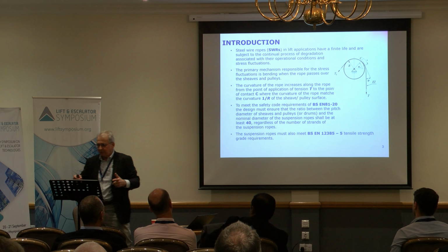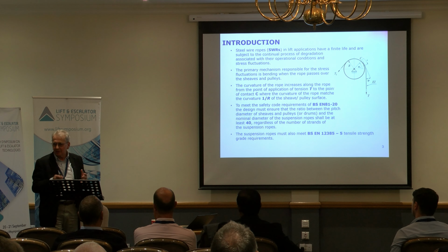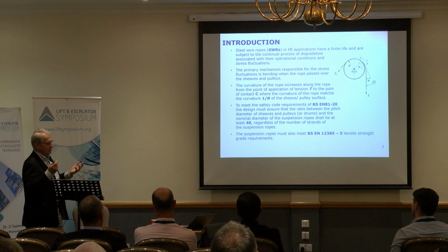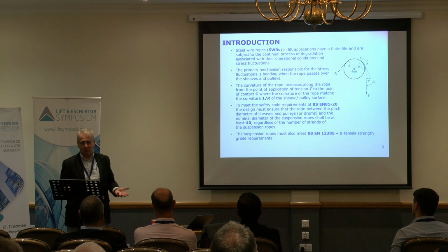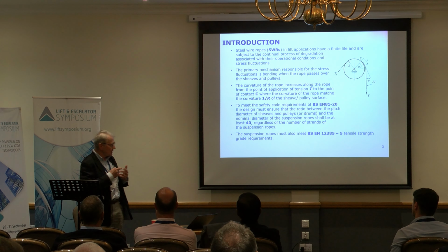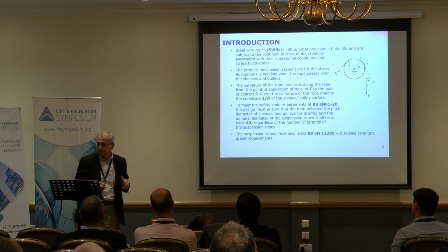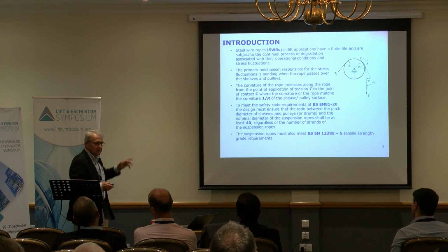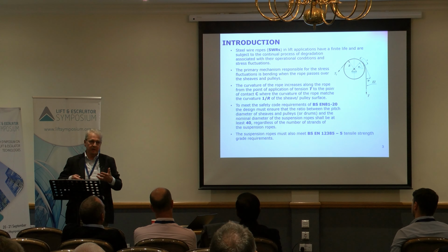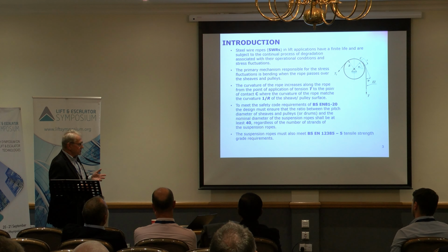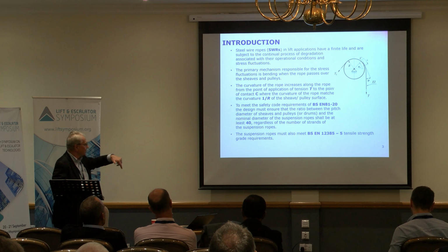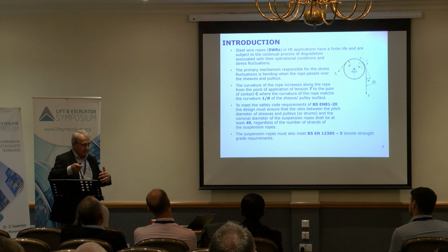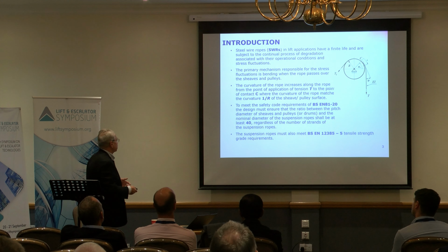That's slightly shifted by a small amount, depending on the stiffness of the rope. When the rope has very small stiffness, or we have a very flexible belt, that is probably almost negligible. However, for large diameter ropes, there is a transition period. So that's about it, how to identify and quantify the changes of the bending stress going over the pulley. And that is a way to do it.